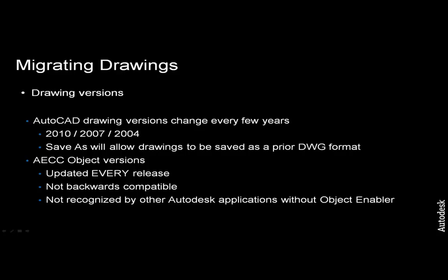It is important to understand that a 2010 drawing file format cannot be opened in an application using a 2007 or a 2004 file format. However, if you want to open a drawing in an earlier version, you'll need to use the Save As command and change the drawing format to one of those earlier releases.